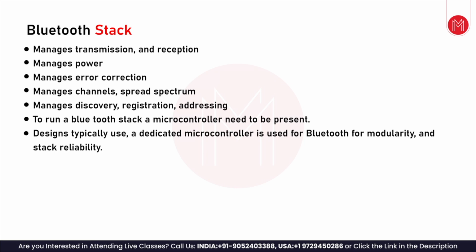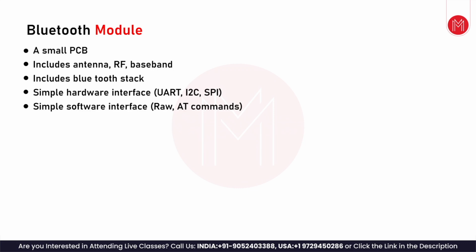So the design typically uses a dedicated microcontroller for Bluetooth for modularity and stack reliability. So you don't have to port the Bluetooth stack onto the application microcontroller. The microcontroller that runs the Bluetooth is separately put into a module, the Bluetooth module. What is a Bluetooth module? It is basically a small PCB. It includes the antenna and RF baseband and all that. It includes the Bluetooth stack and a simple hardware interface. It offers a simple hardware interface, either UART, I2C, or SPI, to the main microcontroller.